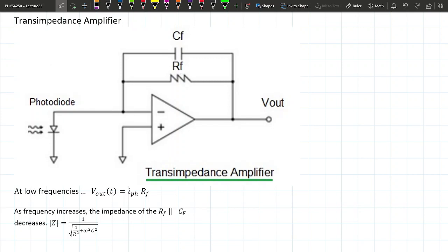You connect your little photodiode here, and then you have the current. Basically, typically you have positive charge going this way, right? You just have positive charge going to ground. You connect this to ground. These little triangles mean ground, unfortunately. Okay, let me just change that quick. Okay, so on some circuit diagrams you have these little triangles. They symbolize ground.